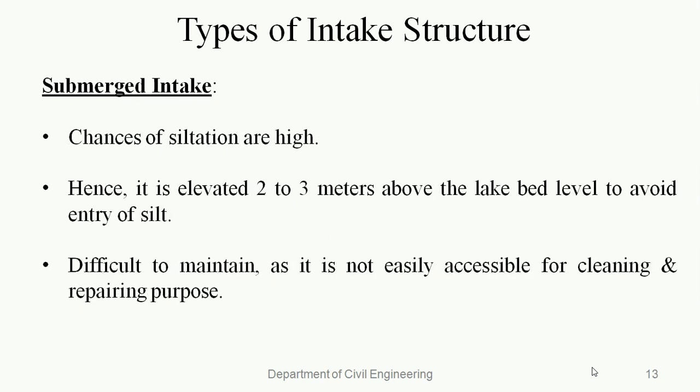There are high chances of siltation in this type of intake as they are located underwater. So, to avoid the entry of silt, it is elevated 2 to 3 meters above the lake bed level. The only problem with submerged intakes is their difficult maintenance, as being underwater they are not easily accessible for cleaning and repairing purposes.